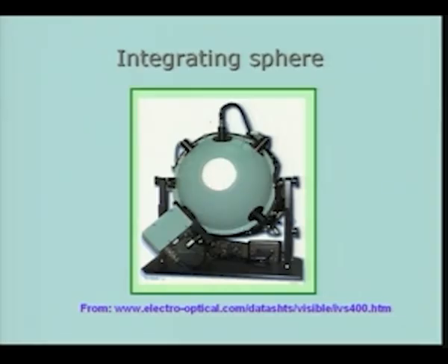So, this can be used for measuring the luminous output of a lamp. Suppose we have a standard lamp for which the luminous output is known, we can place this standard lamp inside this integrating sphere, find out what is the intensity of the radiation leaving by looking at this port and measuring using a detector to detect that radiation. So, you get a reading corresponding to a source of known luminous intensity.